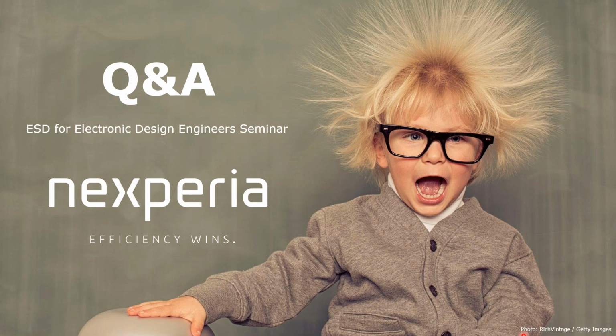The breakdown voltage is higher than the reverse working maximum voltage and gives you an indication at which voltage the transition from not being an ESD protection device to ESD protection behavior happens. To put it very simply, ESD protection devices are Zener diodes, and the reverse working maximum voltage is some voltage lower than the breakdown voltage, and the breakdown voltage is where the curve starts to become exponential.